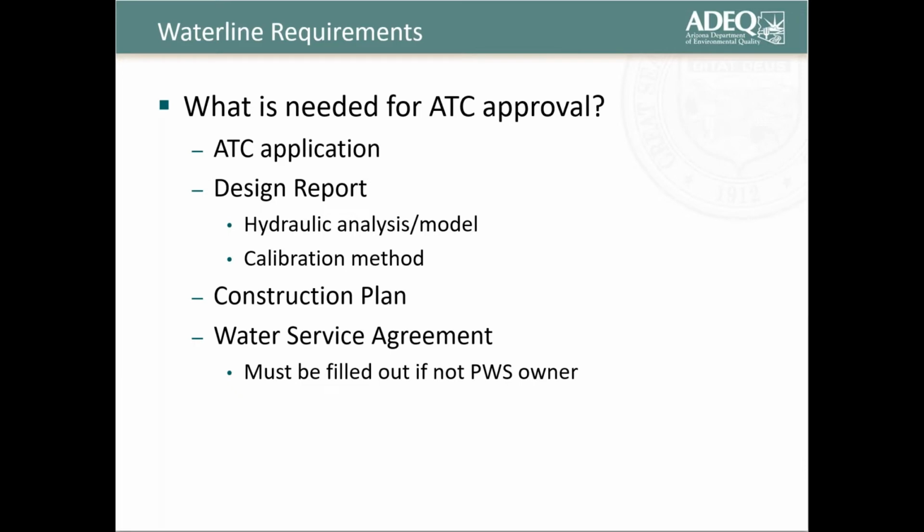And then another deficiency we see pertaining to construction plans is that it's missing a standard detailed drawing. The detailed drawings that we look for on the construction plans are the fire hydrants, air release valves, waterline trench or bedding details, and then also the blow-off valves.